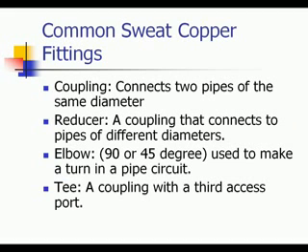An example of this capillary action could be a straw in a glass, as the straw will actually pull the water up into it. Well, take this with metals. We have two base metals with a small gap in between them. We heat the metals up. The filler metal melts and actually gets pulled into the base metal through capillary action.